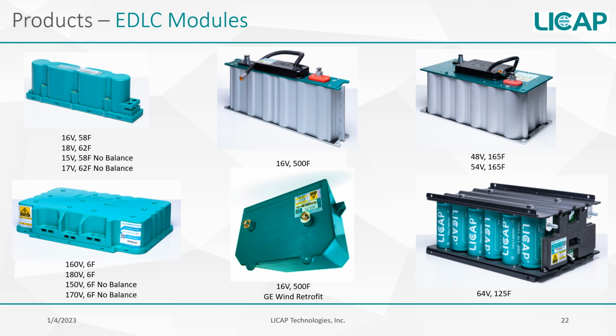In the upper middle, we have a 16 volt 500 farad module that uses 3000 farad 2.7 volt cells. And down below in the middle, we also have a specialized 16 volt 500 farad module dedicated to our wind retrofit applications for GE turbines.